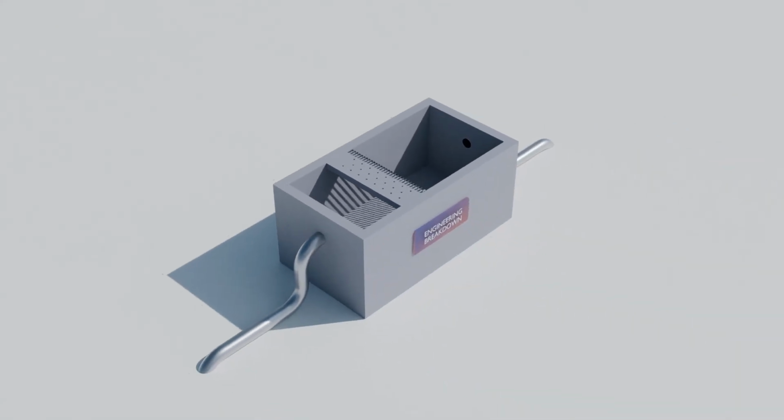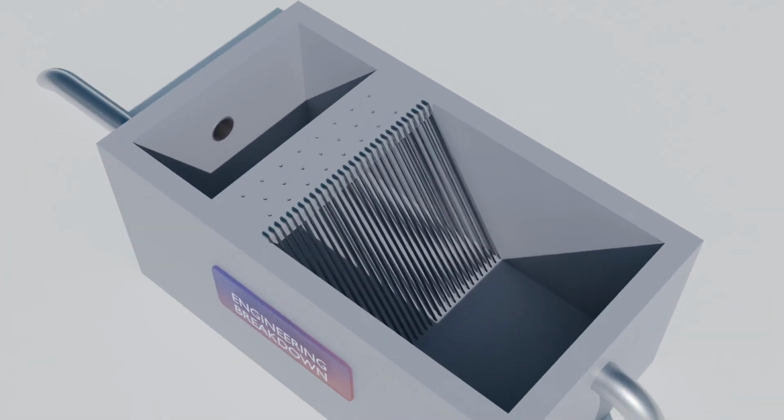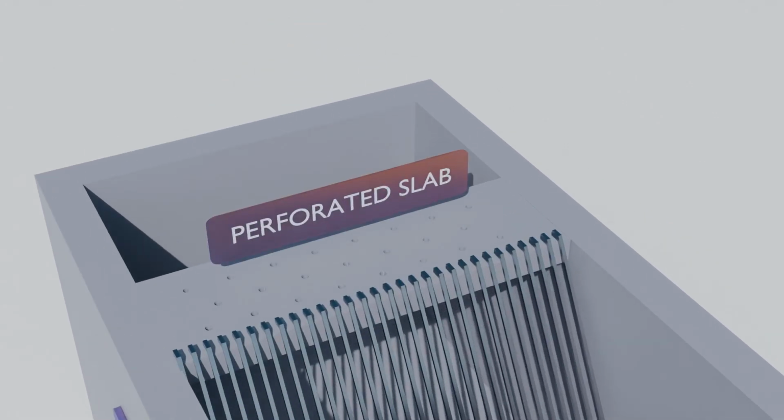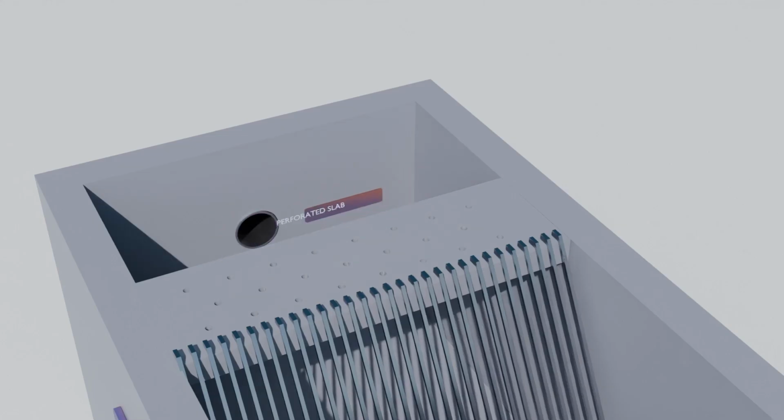Inside the chamber, steel screens are installed to intercept and retain solid waste on the upstream side, while allowing water to pass through. A perforated slab is provided above or near the screening area, enabling operators to stand and carry out cleaning safely. In some chambers, automated mechanisms are used to remove and separate the collected debris. The perforations in the slab allow excess water to drain from the removed waste, making handling and disposal more efficient.